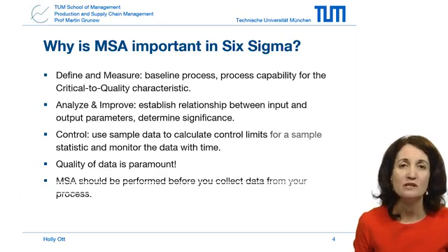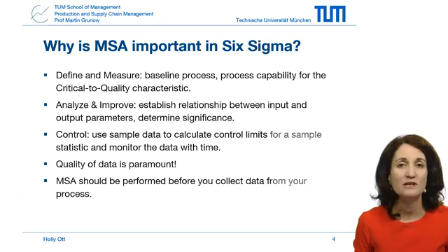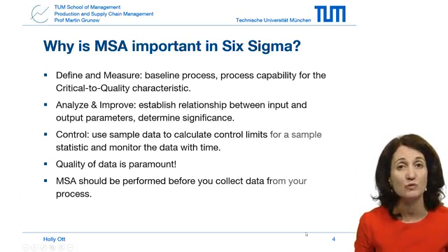When do we use a measurement systems analysis? Well, you do this before you collect any data from your process. For example, if you want to analyze the process capability, you use the measurement system analysis to confirm that the measurement system measures consistently and accurately and adequately discriminates between the parts.